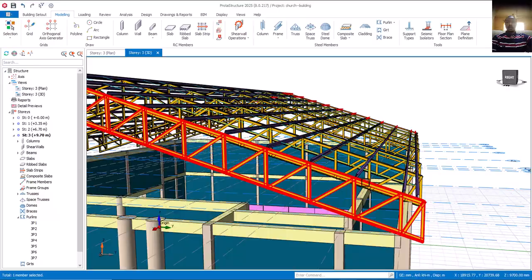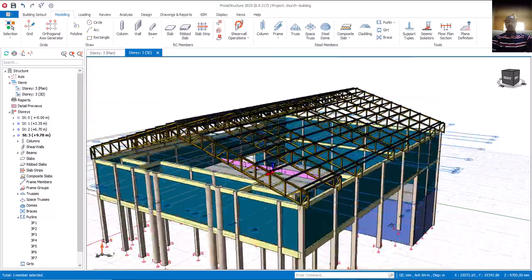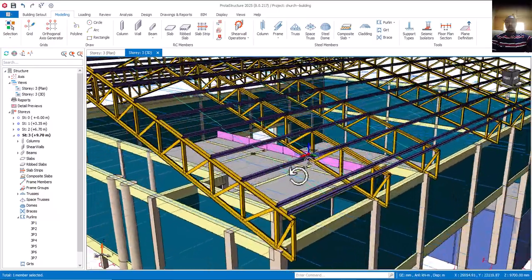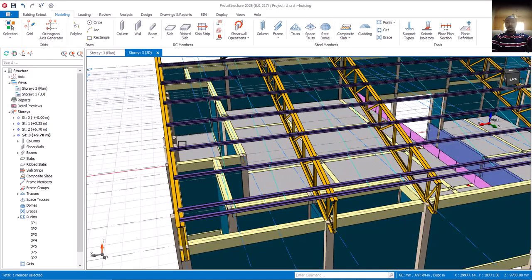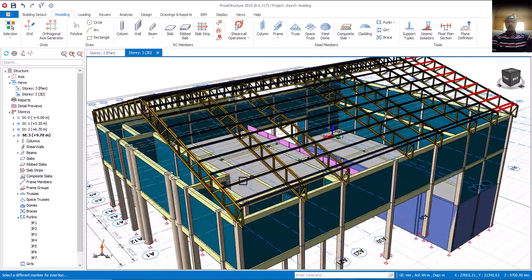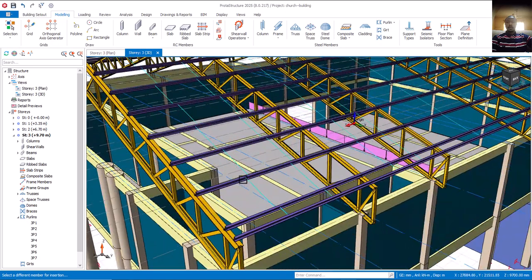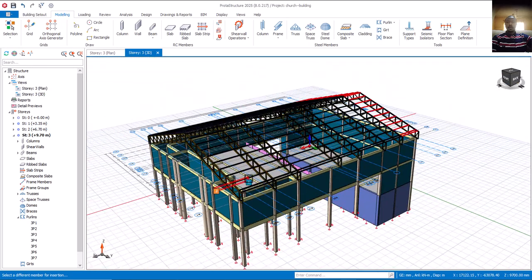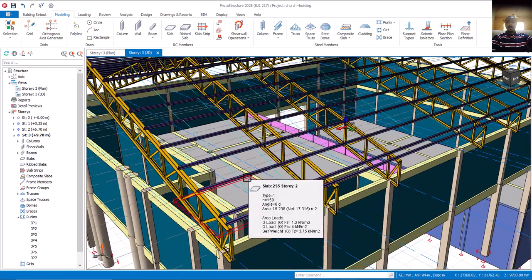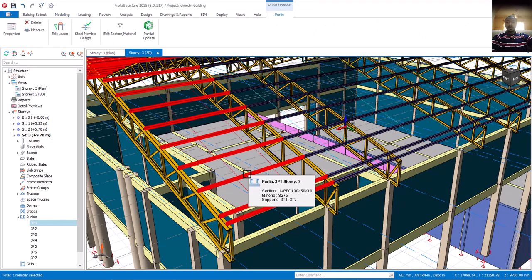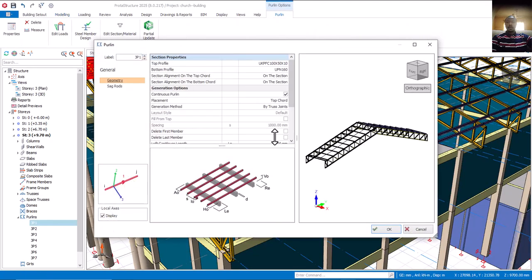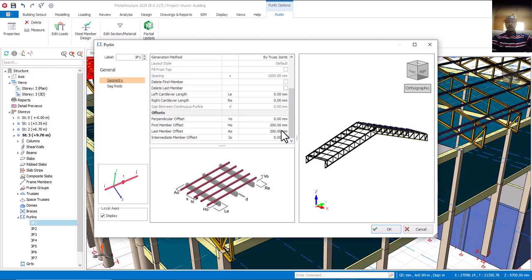The next thing is to put our roofing sheet. But in this case, before we put our roofing sheet, definitely there must be a projection here. Our purlin must project, isn't it, on this other side? So I'll click on this one now. Where is it? Purlin. Okay, sorry, let me escape. Alright, so I'll click on this, double click. Is that okay? Then I'll come down to this place where I have perpendicular offset.